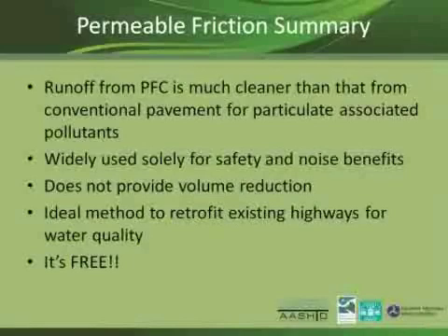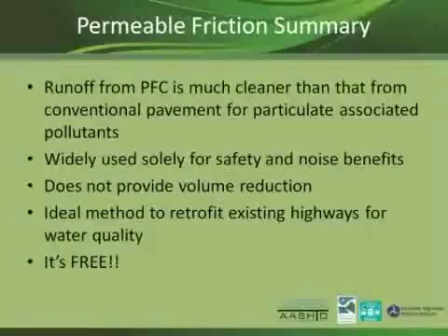And the key thing here is that a lot of constraints have been mentioned by the other speakers. Sound walls, limited right-of-way, elevated sections, etc. This requires none of that. You're just going to go out there. If it's an existing asphalt pavement, you're going to mill it and replace it with PSC. If it's a concrete pavement, you're going to do a seal coat and then an overlay with PSC. So you don't have the ultra-urban constraints.